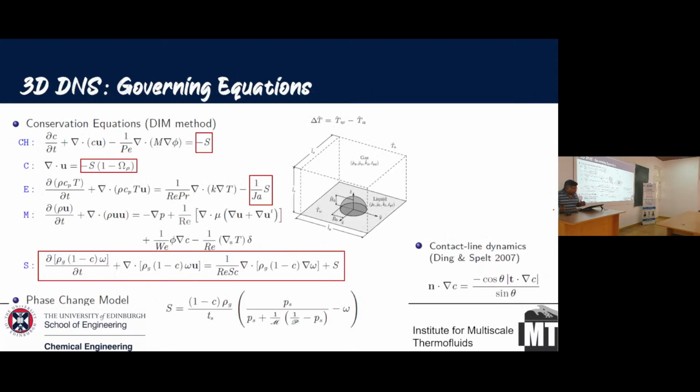So we're going to look at these equations a bit carefully. I don't know how many of you are aware of the volume of fluid method, or level set. Mostly volume of fluid and level set. Typically, in any method where you have a liquid and a gas phase, you have an interface, and this interface will move. One of the standard equations people use to move this interface is an advection equation for the interface.